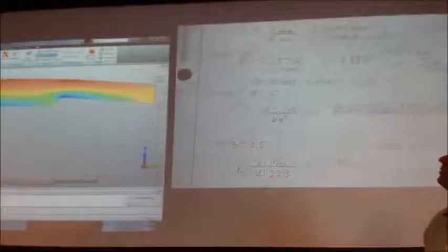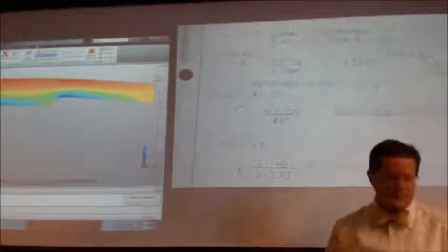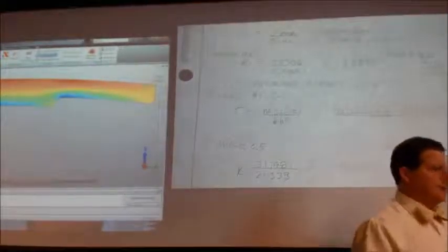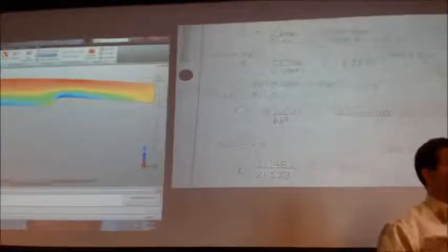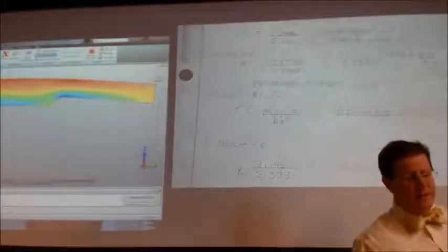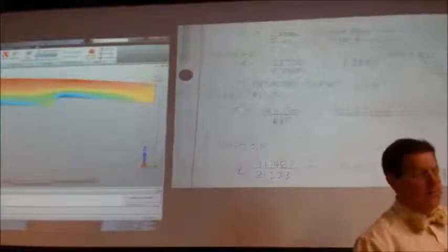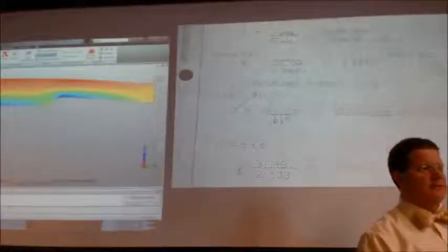So I have a couple calculations here for a couple different mesh sizes. And E-fatigue does not have this shape on it. So these numbers are from the solution manual from Peterson's, which is a big book of stress concentrations.